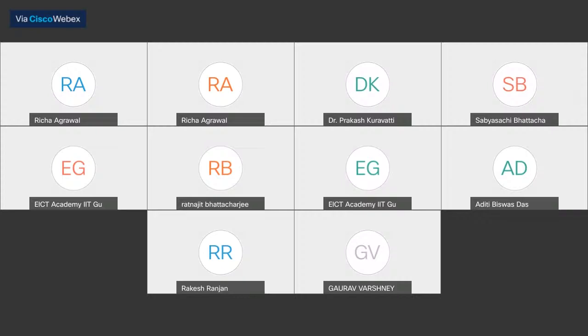Suppose I make an antenna which is linearly polarized, and suppose it is to transmit power with X polarization oriented along X. What we mean by polarization usually is the direction of the electric field. So I have the EX component. And if it is purely X polarized, then I should not have any EY component.